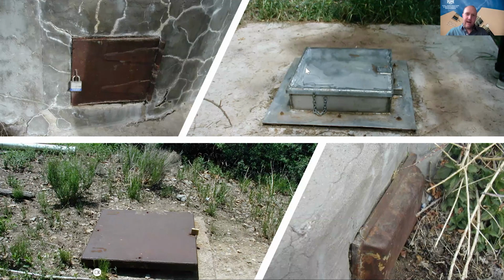You can see that they have these shoebox lids that ideally keep out any sort of contaminant, so it can be considered groundwater and isn't exposed to any outside contaminants such as runoff. This one right here probably would be considered groundwater under the direct influence of surface water, just because it does have that potential contamination.